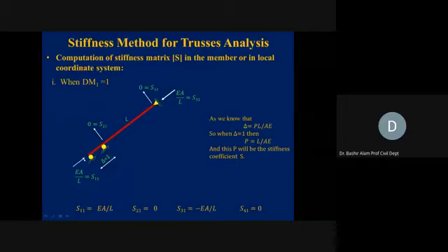You see in that DM1 direction, a unit displacement is given. Look at the rest of the locations: when we provide this roller, it cannot move perpendicular to this surface. It can move only in this direction. At the far end, we need to keep DM3 and DM4 equal to 0. So what is the solution? We provide a hinge there, which can offer resistance in the perpendicular direction and along the length of the member also. So this is the configuration where we can provide DM1 equal to 1.